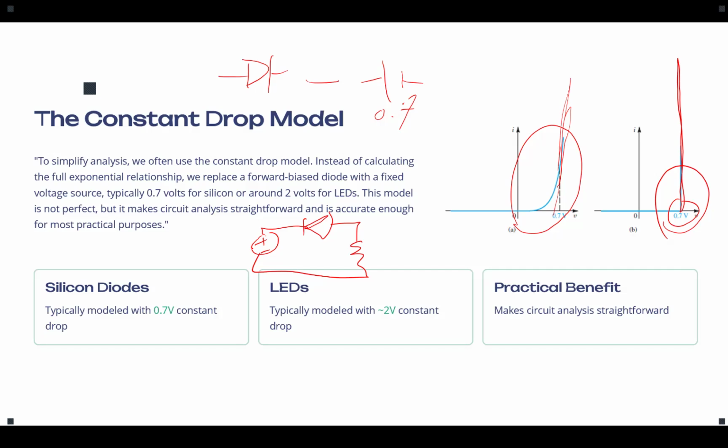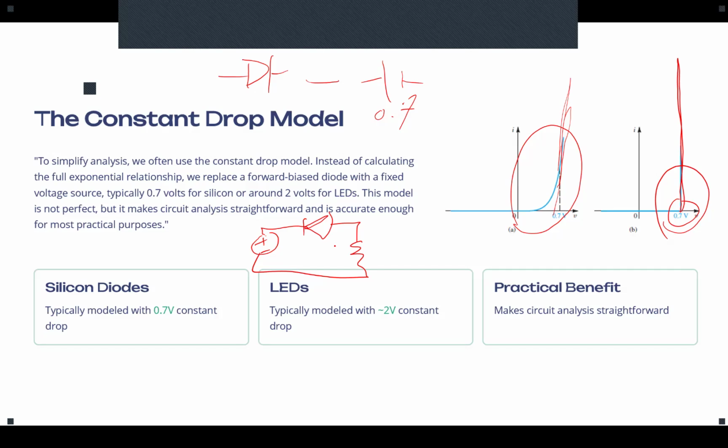When you are out there after your graduation, designing a system, you have to consider the voltage breakdown because you are going to have transient situations in your circuit. You should not exceed the tolerance of your diode. Okay, so that's the caveat. In this lab, we don't go near the voltage breakdown for the general diode. Now, if we are in a reverse bias or a forward bias lower than the voltage on, it's simply an open circuit. So you can replace it with an open circuit and then run the analysis on whatever is left of your circuit.